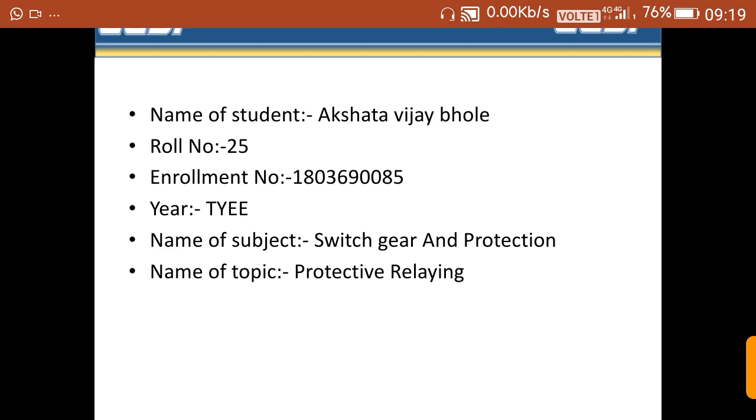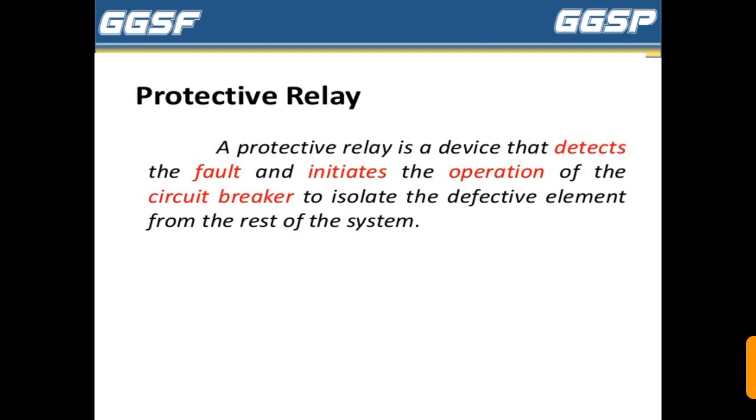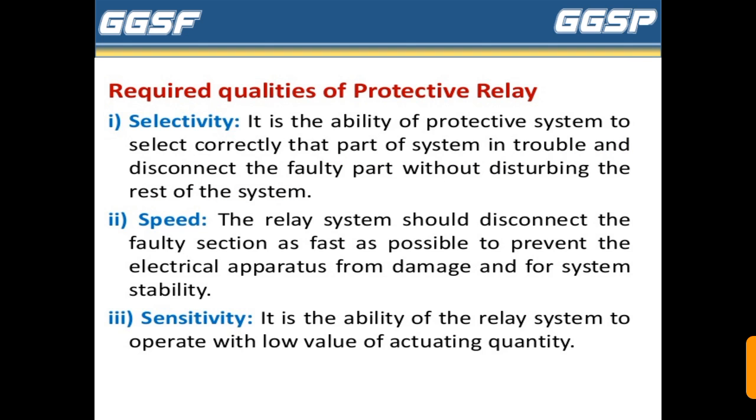Name of subject is switchgear and protection. Today's presentation topic is protective relay. Now what is protective relay? A protective relay is a device that detects the faults and initiates the operation of the circuit breaker to isolate the defective elements from the rest of the system.